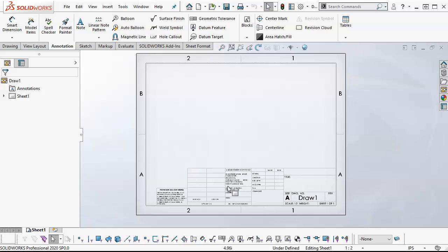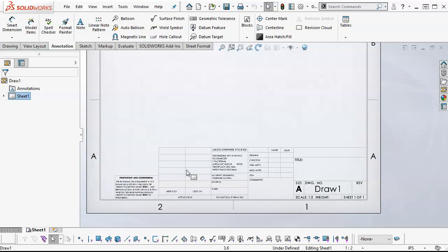So in my opinion, this is a little busy. There's information that I don't need, and my choice is to modify this one or create new. One of the things with a template is our drawing area, our work area, is where we're going to insert the views and populate the dimensions and annotations. And the title block is where we are doing all of the pertinent information: the title of the drawing, the part numbers, the revisions. All of that should come over from the part through its file properties. So our choice is to edit this or to create new.